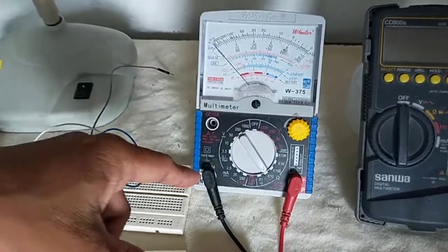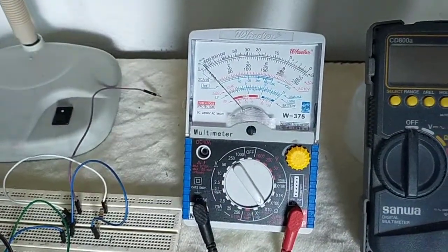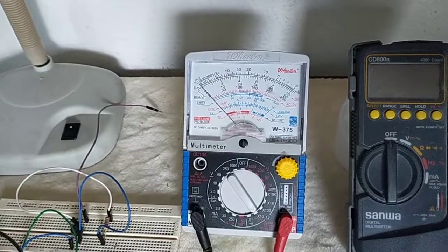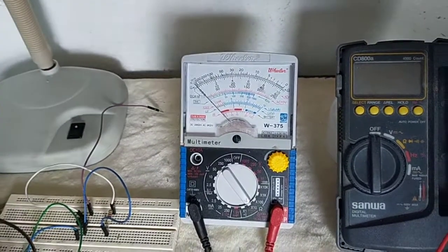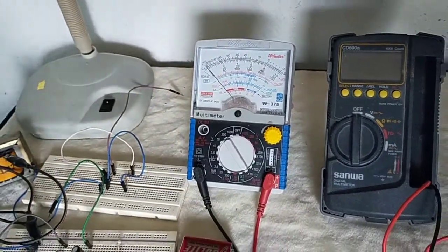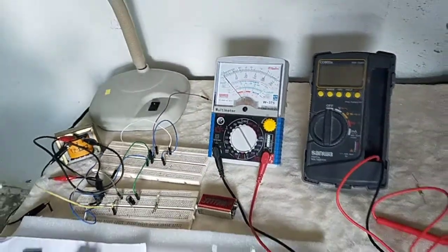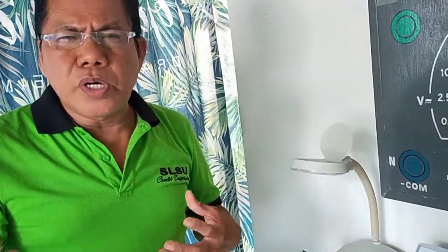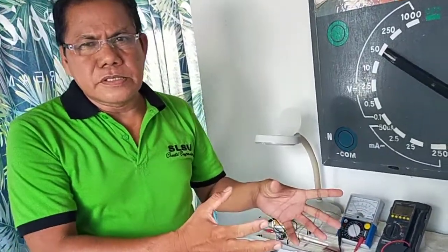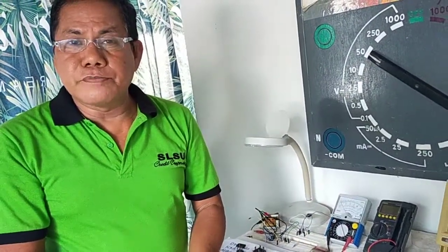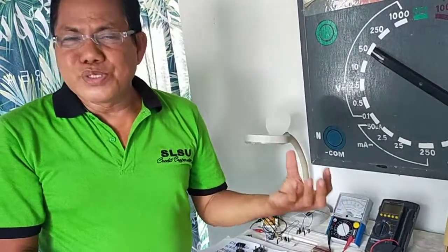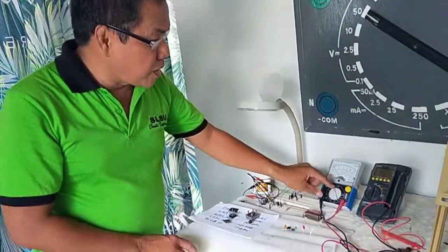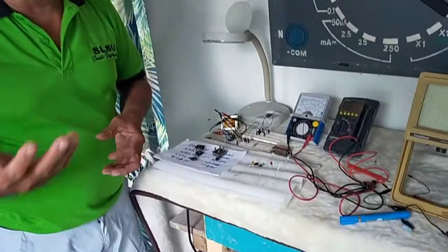It is not recommendable to use times 1 when you are checking semiconductor devices such as diodes, bipolar junction transistors, field effect transistors, UJT, PUT, SCR, diac, triac, quadrac, and ICs. For these semiconductor devices are very sensitive to excessive amounts of current. And remember that times 1 offers a higher amount of current.